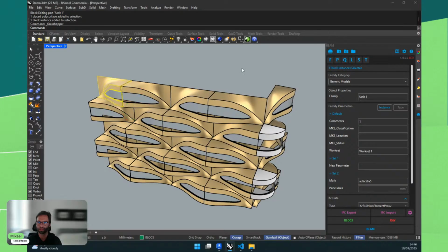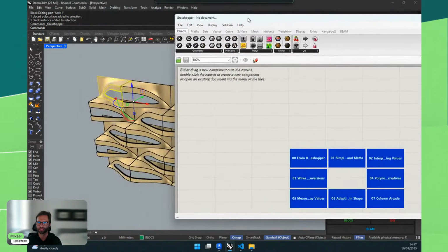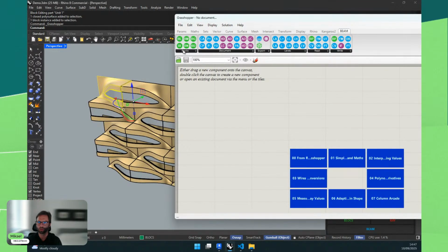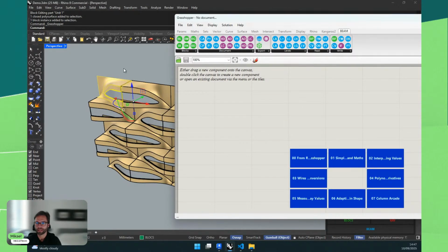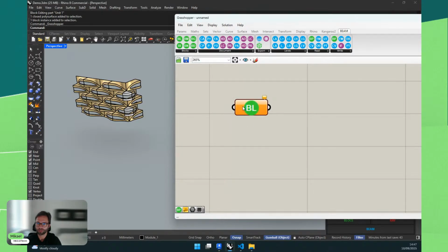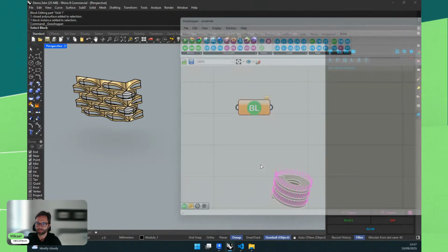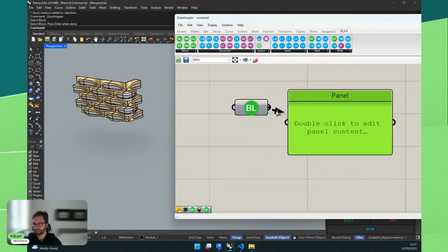So, for example, what you could do, I'll quickly open the Grasshopper here and just show a couple of things. So in BEAM, we have a few block nodes because there was no, at least in Rhino 6 especially, no way to actually select block instances very easily. So we added those to BEAM under the blocks, let's say, group. So you can say block, okay, which represents a block. And then I will say set multiple blocks, and then I can select these blocks. And now I have my blocks selected, all right? So I have my block instances.